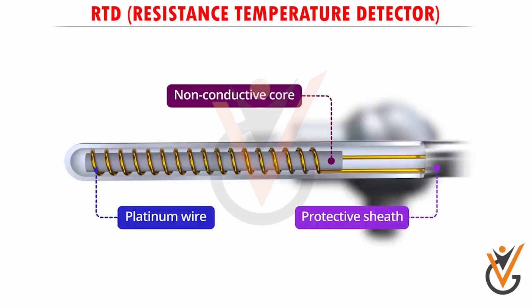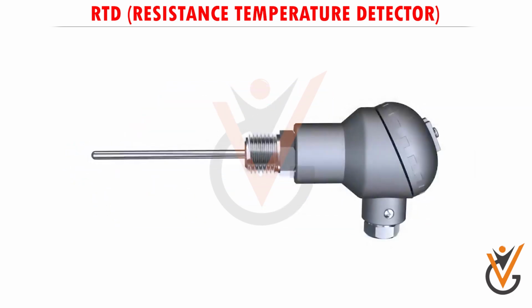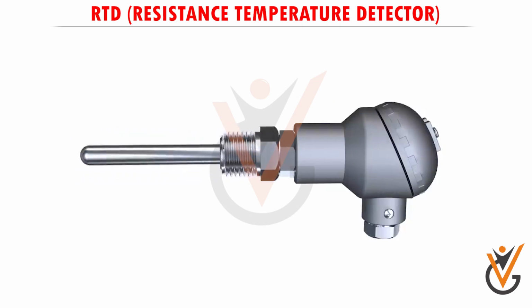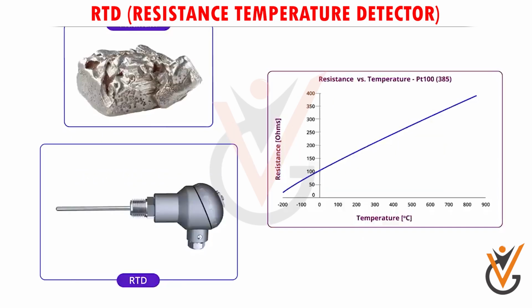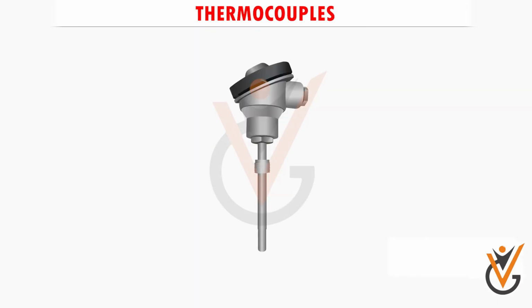Almost all machineries like main engine, generators, tank monitoring system, etc. use PT100 sensors. The sensing resistance of the element used in a PT100 sensor increases with an increase in temperature. See a chart that describes the temperature versus resistance relation.